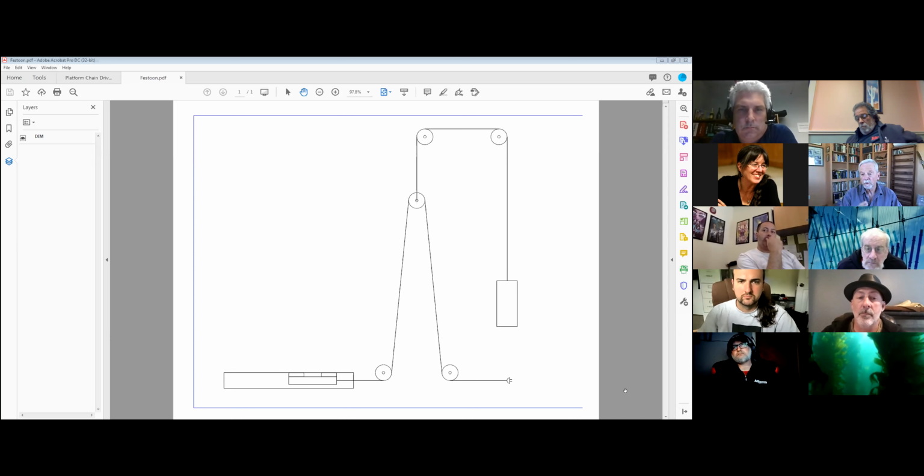And that happened twice, and it turned out to be a real headache. So what we did instead, we set this up. I think you can see in the image here. You have a weight right there that's picking up a pulley, that's picking up slack out of a cable. So as the platform moves on stage, it raises the weight, and that's a solution. I'm not saying it's a good solution, but if you had to punt, that's one way to do it.